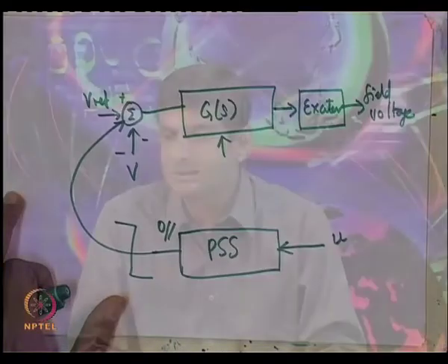This is one important point which should be kept in mind. Whenever you design a stabilizer of this kind, we should ensure that if you have stabilized one particular eigenvalue or swing mode, you should not go and destabilize something else. That is an important requirement of any damping controller, so when designing it, one has to keep that in mind.